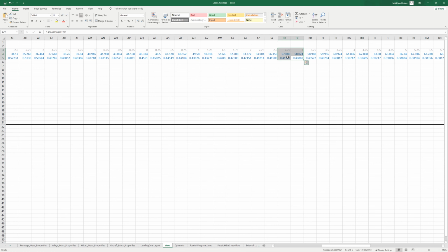And well, you can tell from the design of this aircraft, I mean, the angle of incidence was 3 degrees, so the angle of attack of the aircraft as a whole is almost 0 here. So we're at a pretty efficient configuration in cruise.